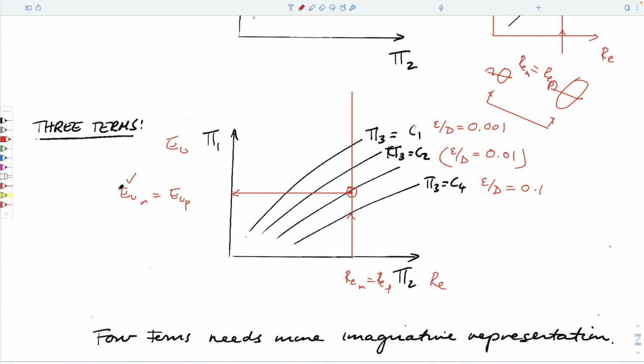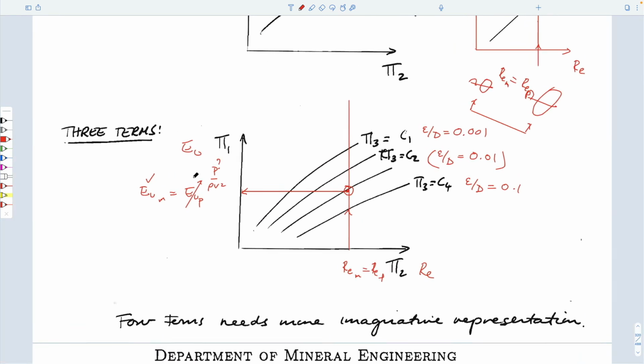We measure the pressure on the model and the density of the fluid flowing around the model. So we know everything about this number. And what we don't know here is we have P over rho v squared. We don't know what the pressure is, and we'd like to find that out. And so that's our last remaining variable. And so that's it. It's an incredibly powerful technique that we've used.